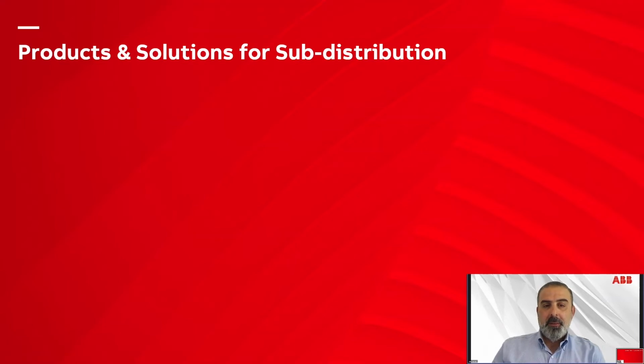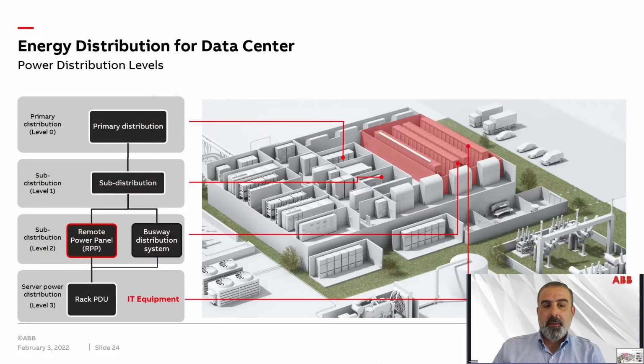If we look at the landscape of a data center building from an energy distribution perspective, and typically any standard installation, it starts with the low voltage side on the medium voltage transformer, feeding primary distribution protection, usually named MDB, main distribution board, flowing downstream to the sub-distribution level, and then focusing on what really matters to a data center, the energy distribution at IT equipment level. Meaning white space areas where all the IT racks are installed.